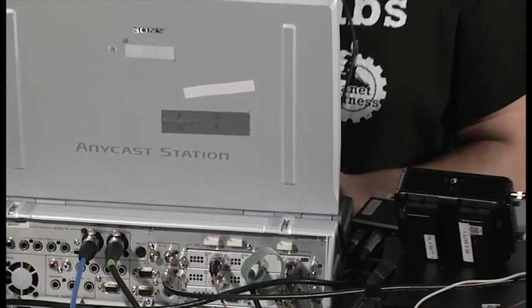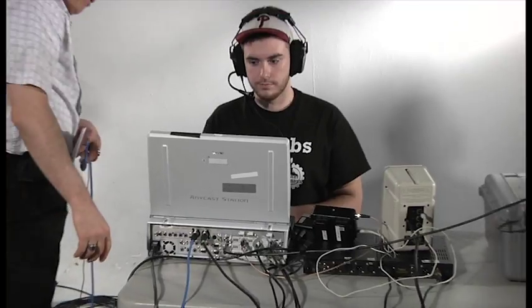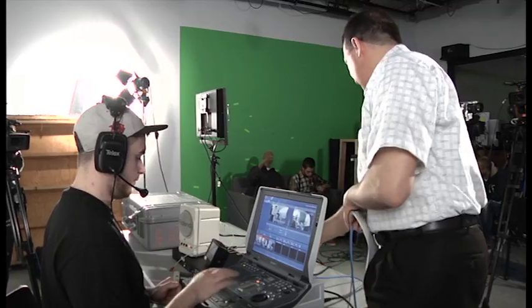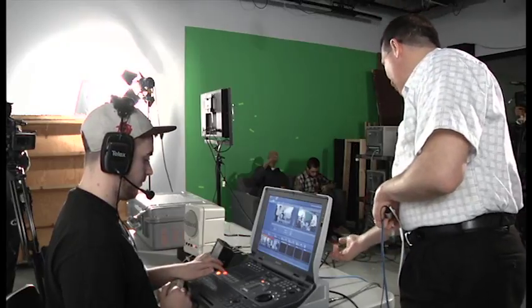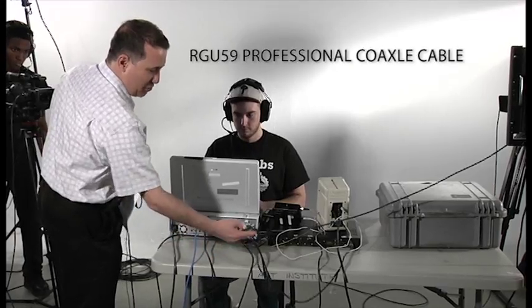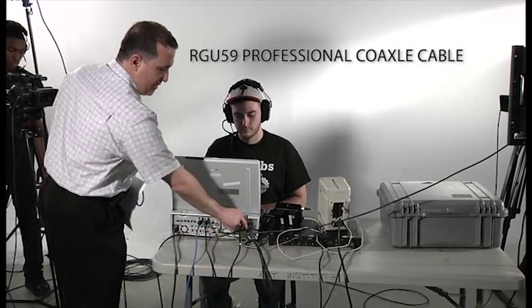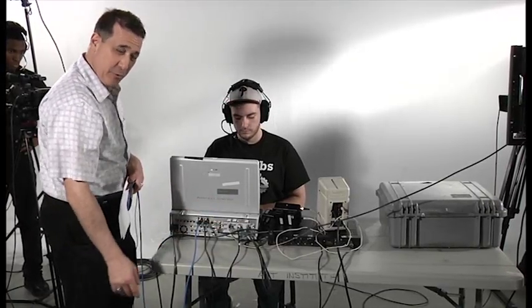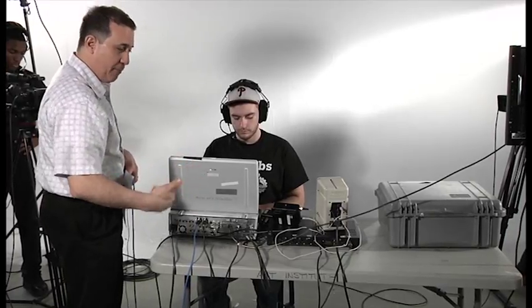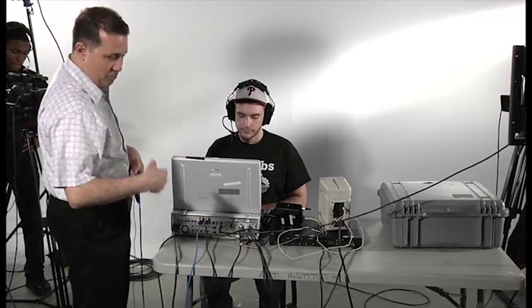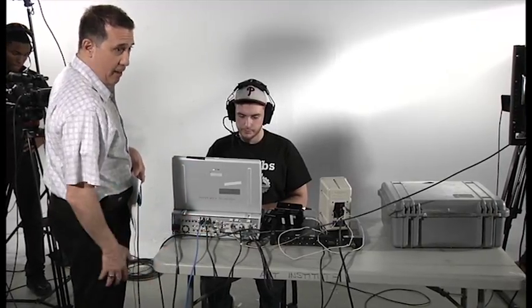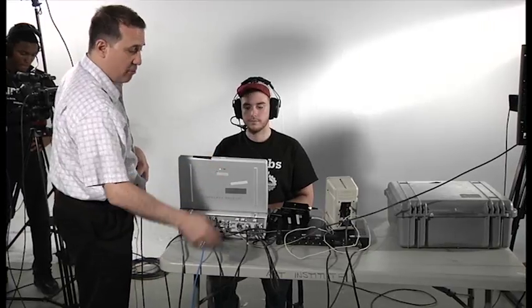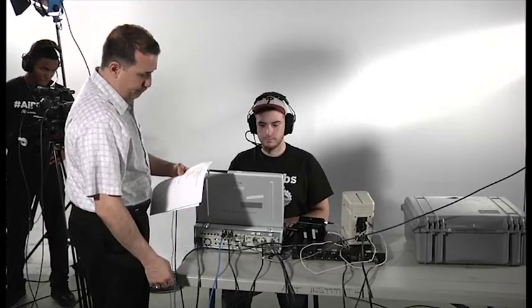So on this device, we're using traditional, generic BNC to BNC cables, meaning the cable is a normal RG-59 professional-level coaxial cable with BNC tips. These are not actually SDI cables. You could buy true SDI cables, which are BNC-tipped coaxial cables, but made to carry a stronger signal or maybe a faster data rate. We just use traditional BNC and we've been successful with that.